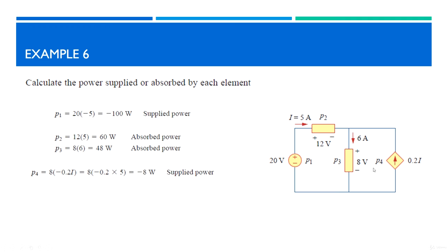Now let's go to our element B4. B4, let's see its power. It is a current source. So the power of it is equal to the voltage multiplied by the current. Okay, but remember something, which will be discussed later, that here this element is parallel to this element. Okay, you will see that this node and this point is common here, and also this point and this point are common. Okay, so the end and the beginning of each element are the same.